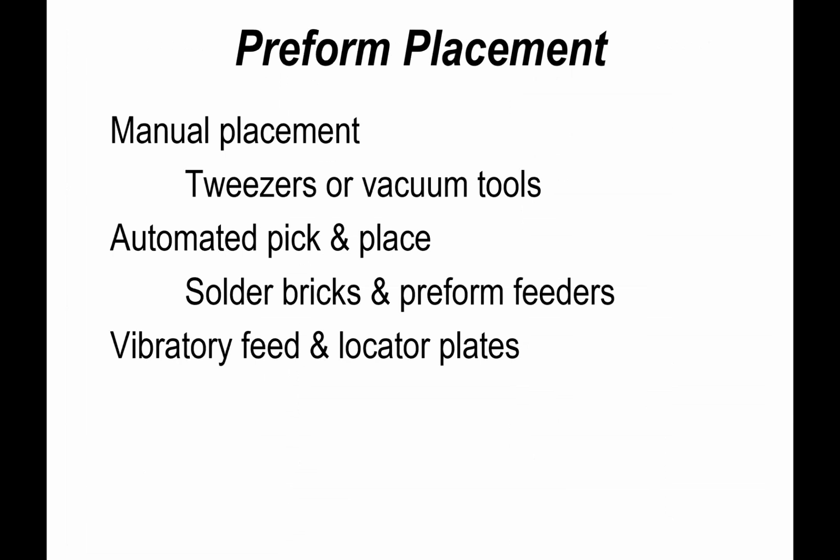Automated pick and place, well, it's fair to say that in the last sort of 5 or 6 years, possibly even longer, there's been a lot of interest in the use of solder bricks, and I use that term, so I'm non-commercial, I'm not using commercial terms, but basically we're talking about a lump of solder which we're putting into or around a joint, and that's predominantly to improve the performance for pin and hole intrusive reflow.